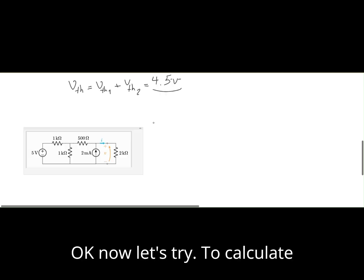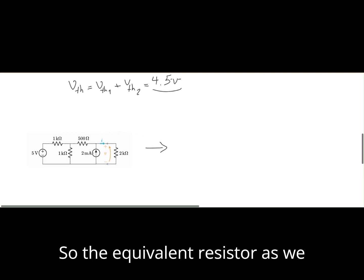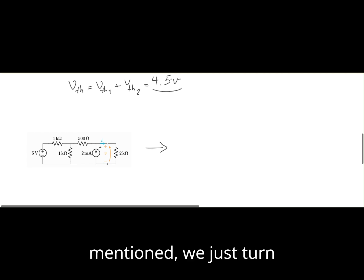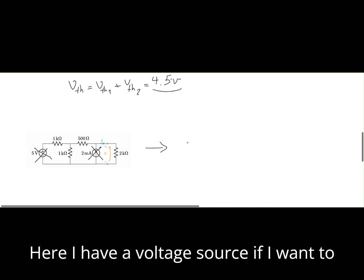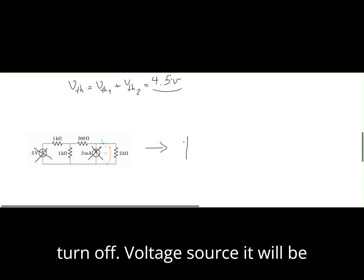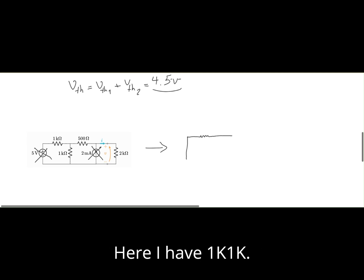Okay, now let's try to calculate the equivalent resistor for this circuit. So the equivalent resistor, as we mentioned, we just turn off our power sources. Here I have a voltage source. If I want to turn off a voltage source, it will be replaced by a short circuit. Here I have 1K, 1K.